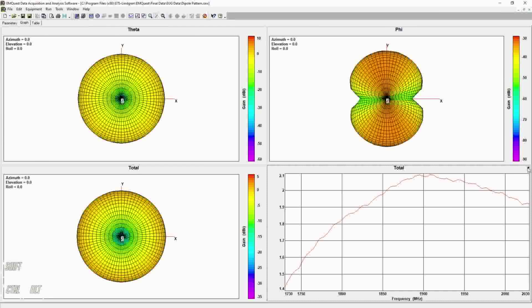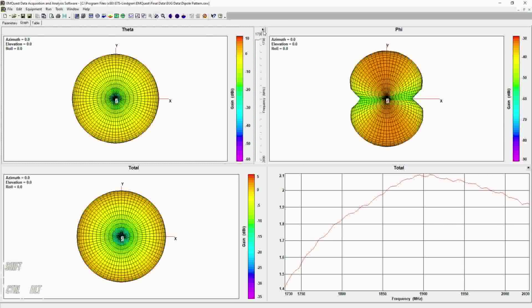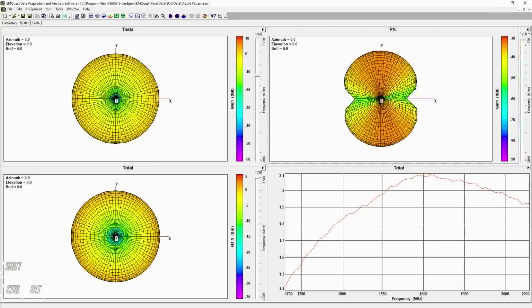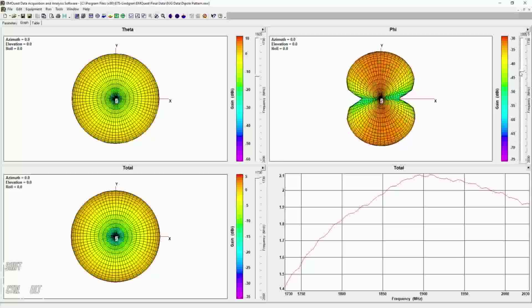What you might not have realized is that if you hover on the corner, anytime I've got a multi-dimensional data set that has been reduced so that I'm not looking at all of the data, there's this little flyout. If I hover in the upper corner of a graph and that little arrow pops up, that gives me the flyout, and now I can drag through as a function of frequency. Of course, that graph doesn't change much. This one here, we can tell there's a little bit of variation.